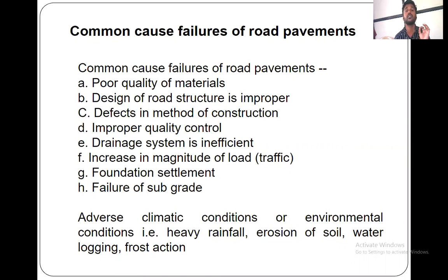Defects in the method of construction. Suppose I have given the proper design, but while doing the construction, some defects remain: proper thickness is not maintained, proper aggregates are not used, proper proportion is not maintained by the laborers because they are unskilled laborers. We have given the proportion with the proper calculations, but they have not used the proper mix design calculations. Whatever the cement quantity, sand quantity, aggregate quantity, that mix proportion, if they have not used it.